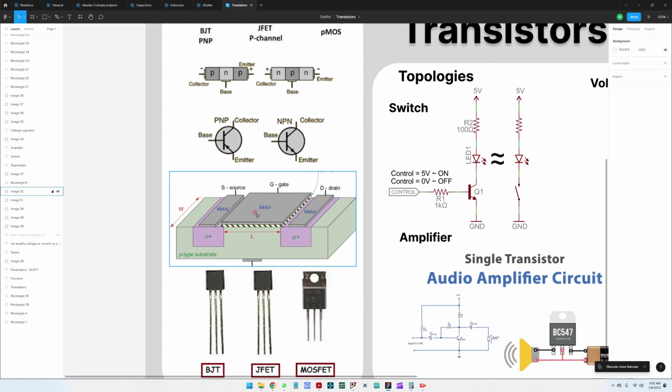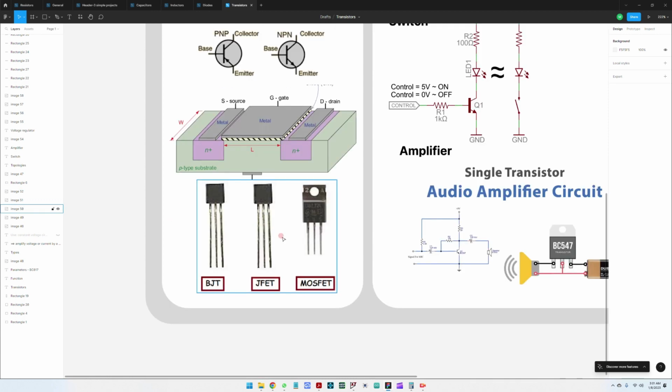The fact that this is acting as a capacitor here is one of the main reasons why MOSFET transistors can switch so fast. So MOS transistors, you would see them in all power electronics applications where you need very high switching speed. Most of the power supplies that I design are using MOS transistors. A bit going forward, let's look at how they look in real life.